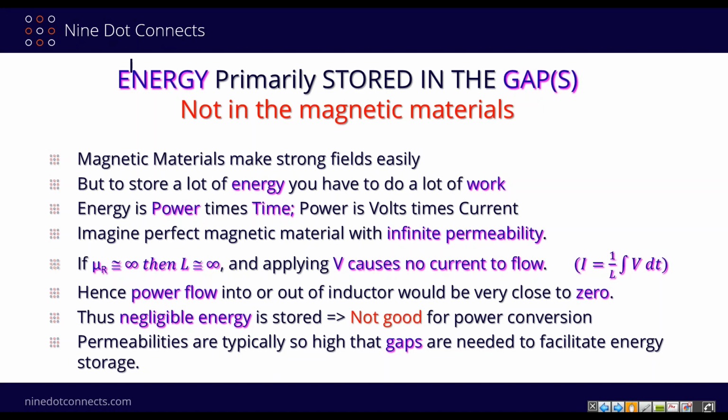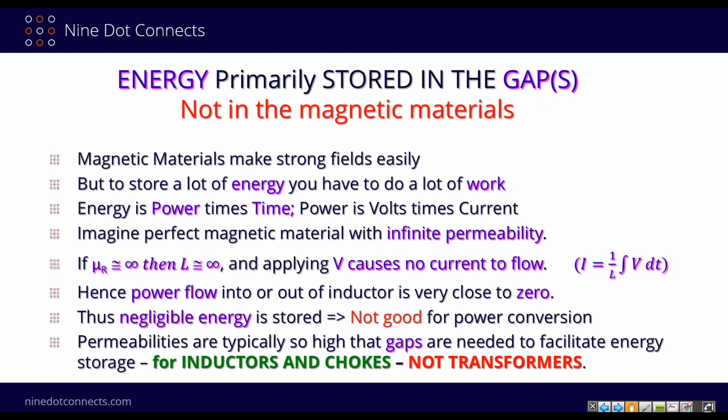Permeabilities are typically so high that gaps are needed to facilitate energy storage. Now remember, I'm talking about inductors that are intended to store energy, but not transformers. Transformers do not store energy by definition. You try not to store energy in a typical transformer.